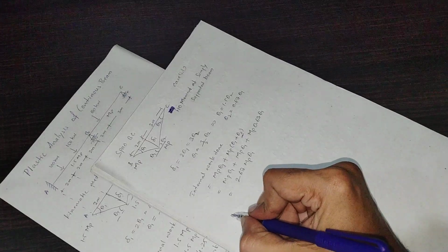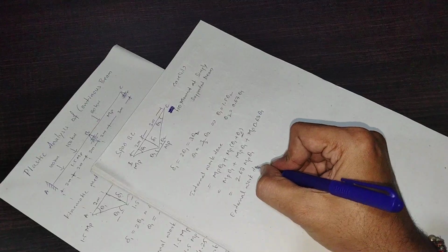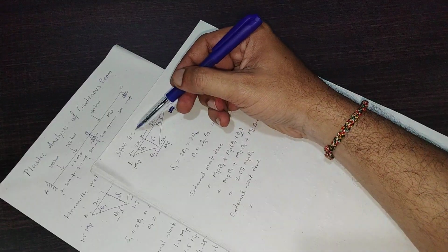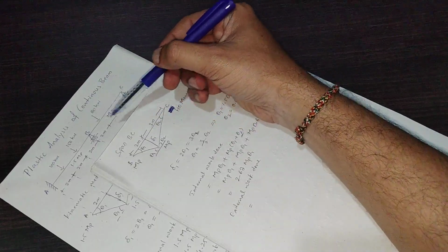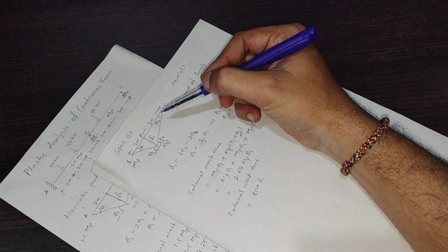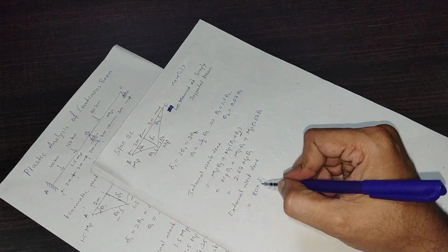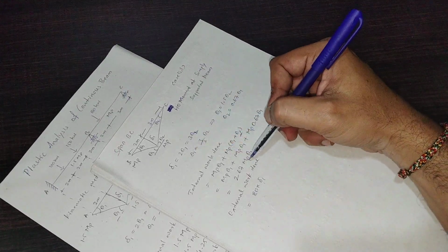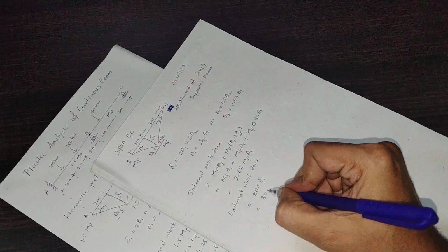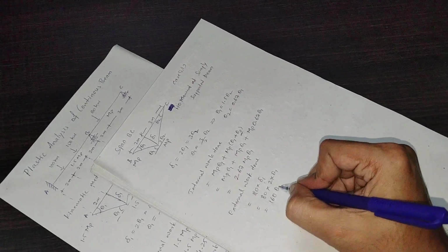Now external work done. So external work done is the load times the deflection under the load. So the load is 80 kilonewton, and the deflection is delta 1. So 80 times delta 1 only, because other than this 80 kilonewton load, we do not have any other loads on the span BC. So delta 1 can be substituted as 2 theta 1, because internal work done is in terms of theta 1. So 80 times 2 theta 1, which is 160 theta 1.